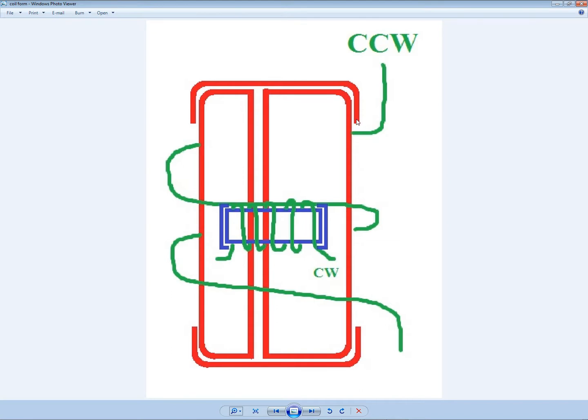then the edges of the cap point directly into the coil, collecting the magnetic field coming out of both ends of the bobbin and redirecting it, because that's what all iron does. It doesn't shield. It simply redirects the geometry of the magnetic field surrounding that metallic object, and it redirects it back into the coil coming out of the edges, the circular round edge of this cap.